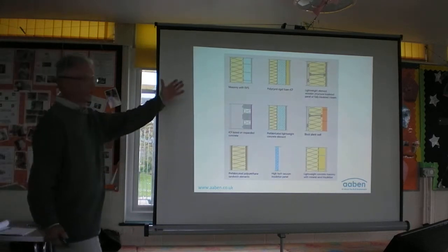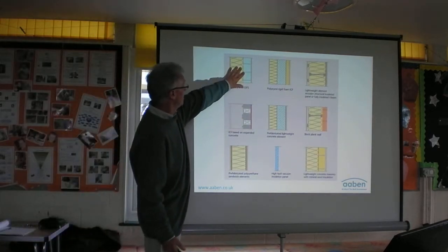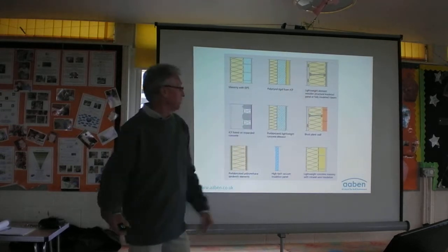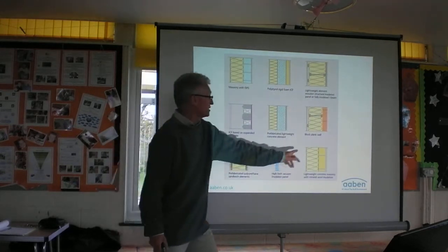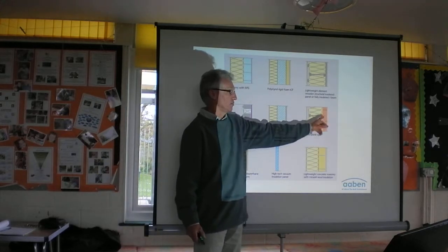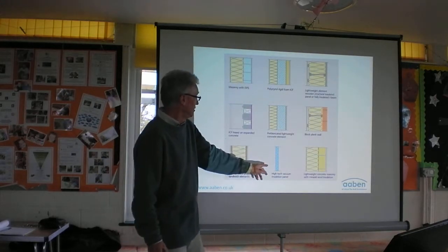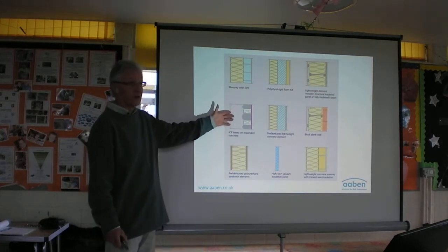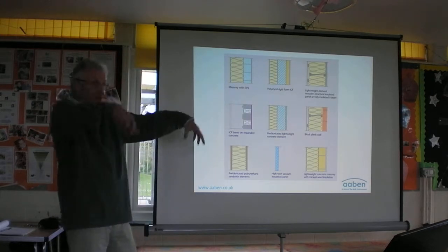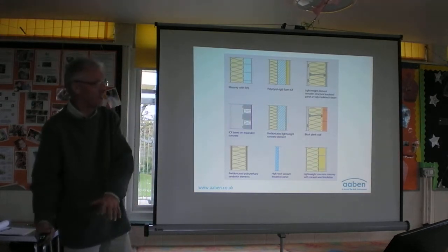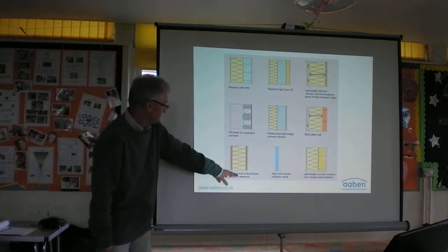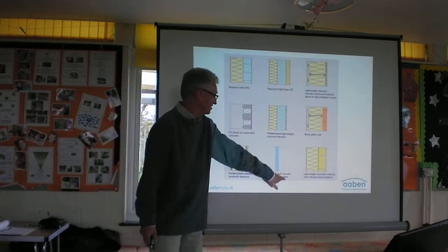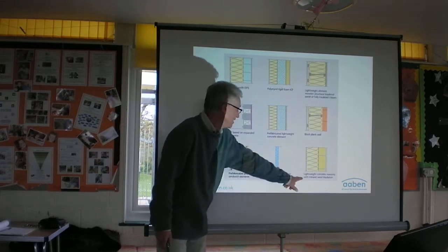So you can use different forms of structure. Masonry, external insulation, lightweight wooden I-beams, which is what we build in. Massive block plank wall, CLT, very expensive. Not sure about that. Prefabricated lightweight concrete, insulated concrete formwork, the sort of Lego bricks that you pour concrete into. Not very sustainable from a cement point of view. SIP panels. High-tech vacuum insulation. Look at how thin that is. It's great. It's 70 quid a metre.